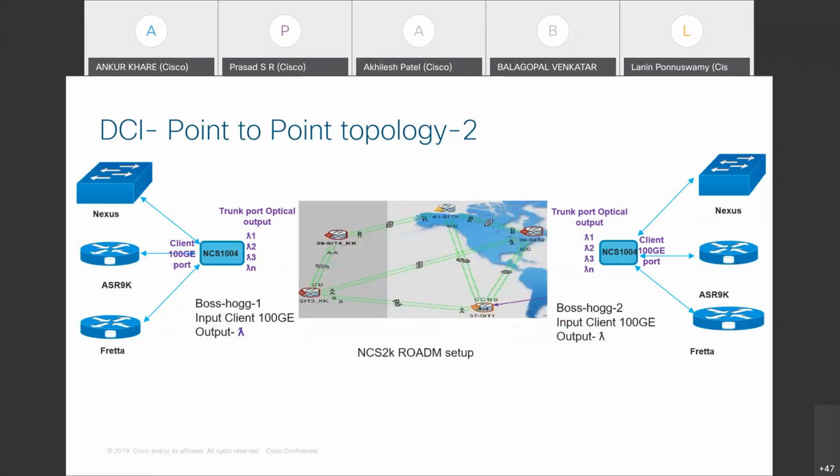But in the ROADM, it allows us to reconfigure the wavelengths, and it has a new concept called flex. In the flex spectrum, within the same spectrum, 1530 to 1565, you can use more wavelengths. You do not have a fixed channel spacing between two channels.